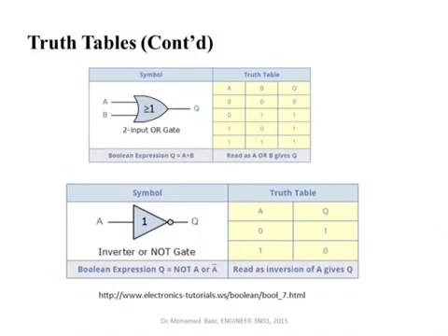The NOT means you apply a logical variable and the output is the inverse of this variable. If this variable is true, then the output is false. If this variable is false, then the output is true, as given by this truth table. And again, this means that if I put a high signal here at the input, 5 volts, the output will be logic 0, which is 0 volts, say. And if I put here a low input, or logic 0, the output will be logic 1 or high signal.